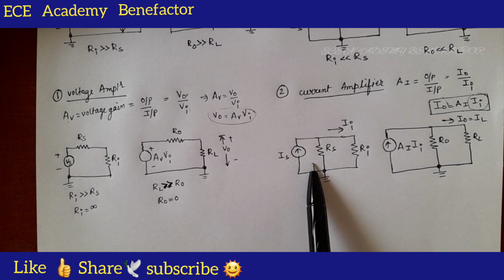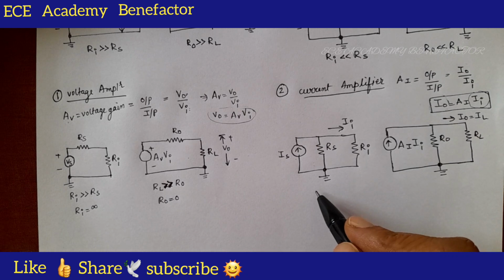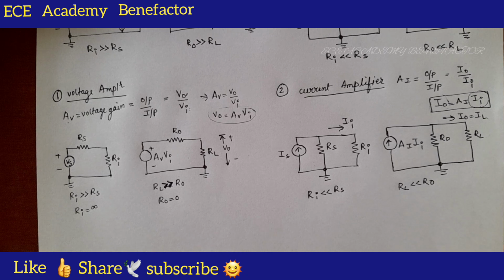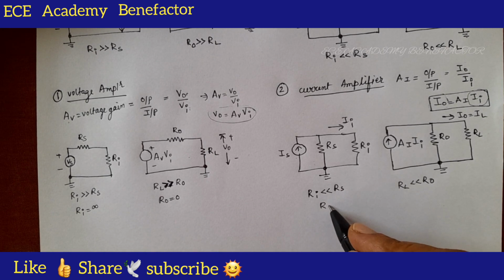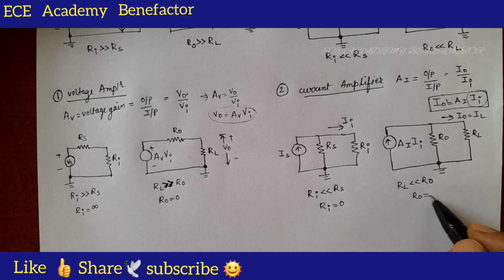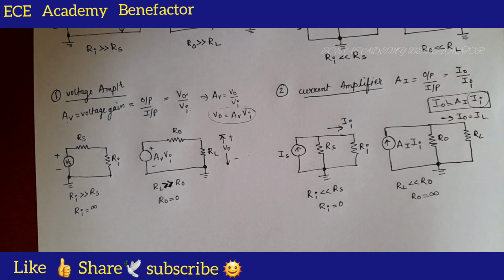So, how can we decide this? Based on this equation. What is the condition for a current amplifier? Ri is very small compared to Rs, and RL is very small compared to R naught. So, if Ri is very small, the ideal value of Ri is 0. RL is very small, so R naught is infinity. In this way we can draw the current amplifier.